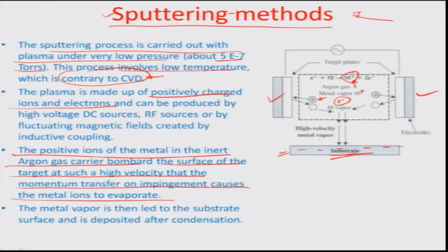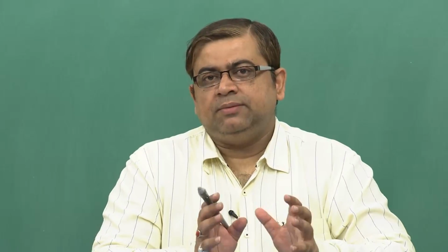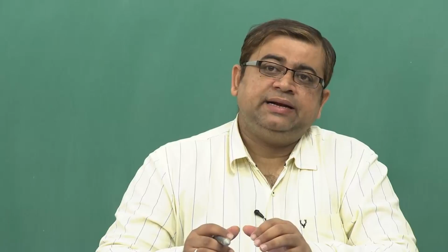However, there is a downside of the sputtering process when we talk about a combination of lithography and sputtering. If we do not have the right parameters for the sputtering process, the film of resist, which is a sacrificial mask coating on the substrate surface, may get damaged, sometimes highly cracked, because of the continuous action of ion bombardment on the surface.